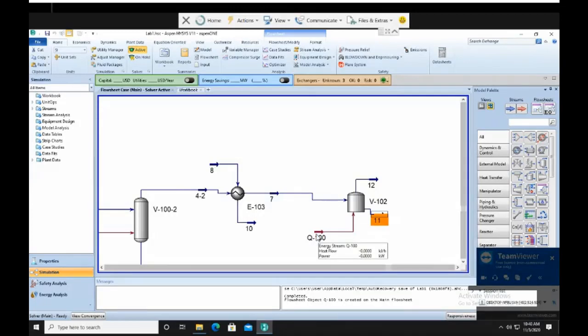Okay, if you are running it at a 4-season country, when it's winter, you have to put in a heater. Or you can reduce the pressure somewhere, I don't know. So if it's a hot country like Malaysia, constantly 35 degrees Celsius, definitely you have to put in a utility to keep the temperature in the tank at 10. Unfortunately, Hysys does not read the ambient temperature, so you have to use your weights.